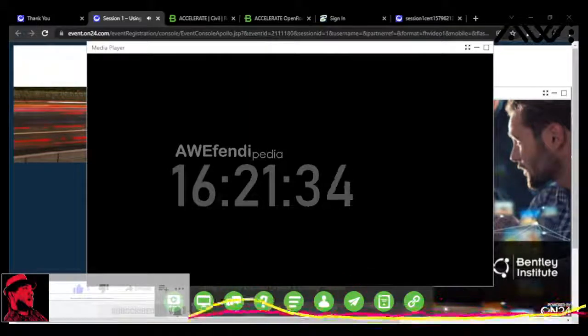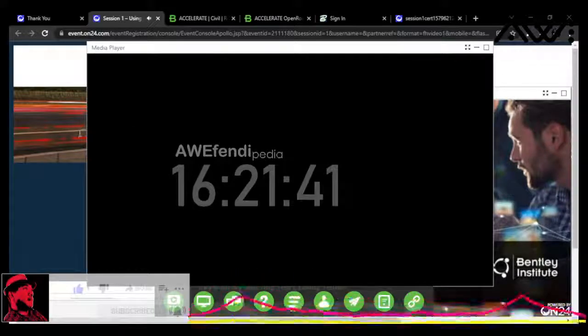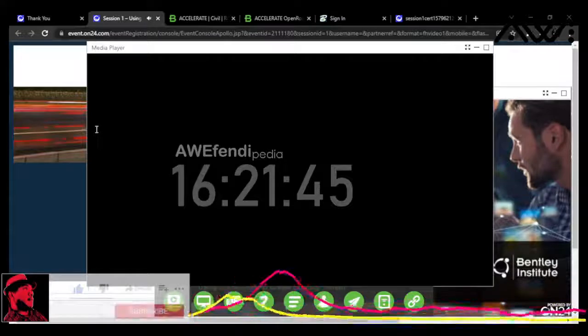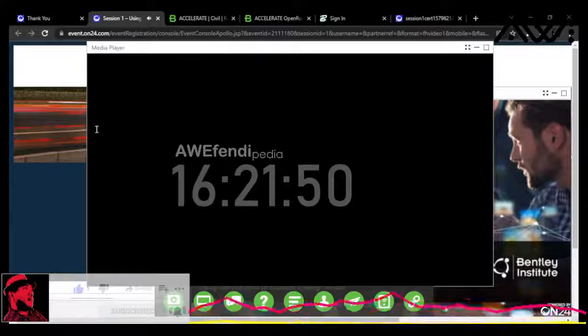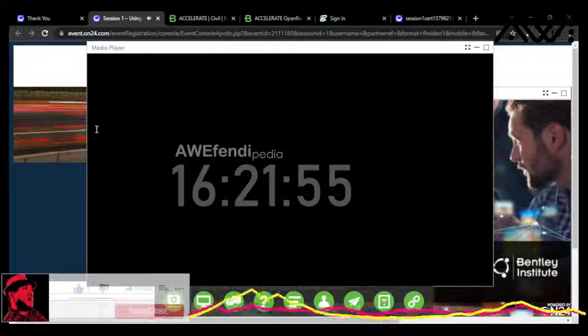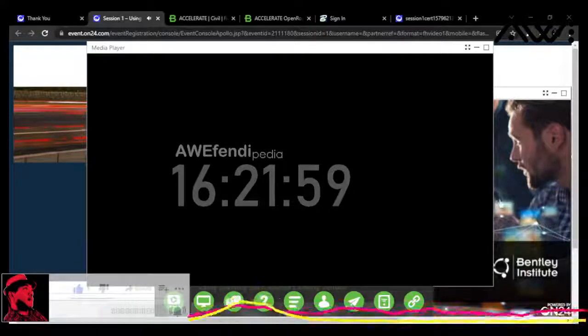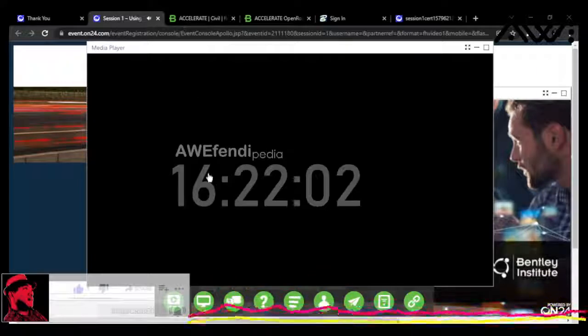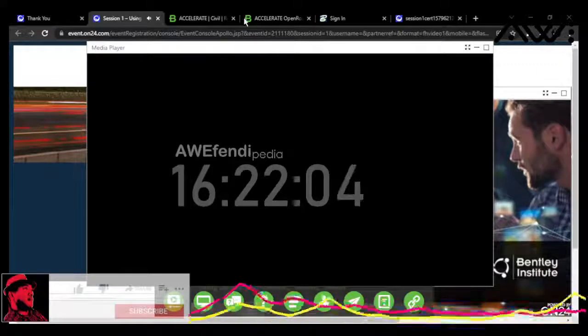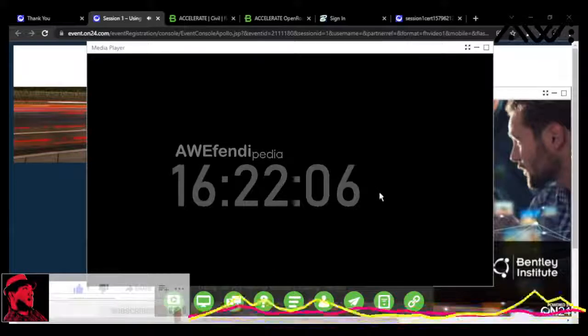I'm going to type in 5278 and press the tab key to accept that value, and then hit the accept button, and it'll draw my line string up there. So again, these edits that I've made by changing the string numbers, by adding a control code to join point, by adding a start code to start a new line, all those are staying within the bounds of using linking codes to draw my line strings for me. So let's go up and talk about how we can use point lists to do the same kind of edits.